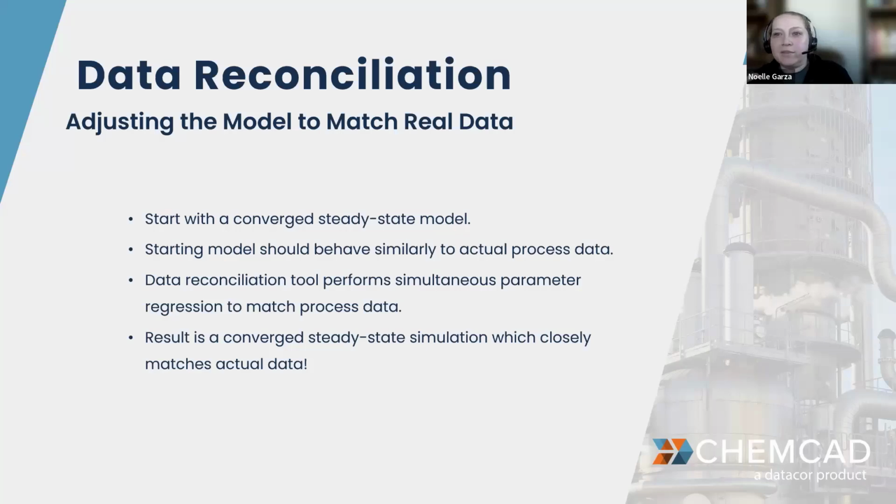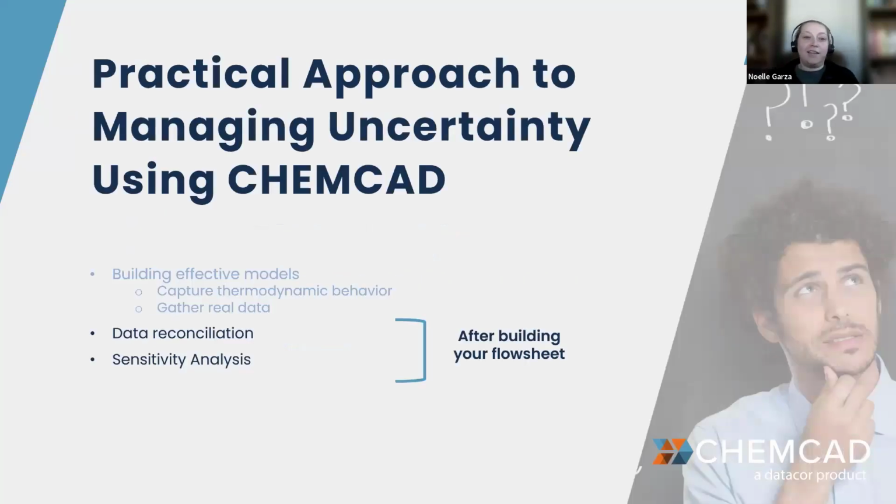And this is a piece of the puzzle if you've heard of digital twin technology. A big piece of that puzzle is data reconciliation. You have your process simulation constrained to first principle physical models, and you're improving that to match real world behavior, real world data. So this is a piece of that puzzle in that digital twin, if you have high fidelity models that you're hoping to use to get very accurate outputs. Okay, so that's just a little side note about data reconciliation.